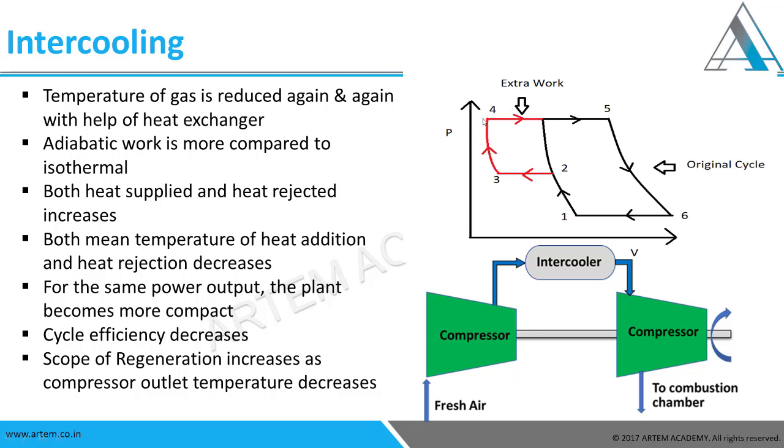That we will be giving through the compressor. But if, using the intercooler, we take this path, this red portion amount of work we don't have to give again. And this is how the adiabatic work becomes less and we become somewhat close to isothermal work. That is how we are giving less work in the compressor and saving our energy. And this helps us to increase our work output. So this is the whole concept of why we are doing it.